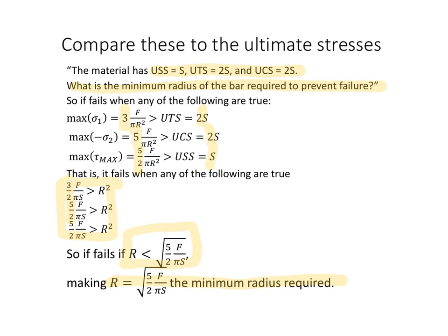So that's this process in brief for one problem. In general, we won't see that the loads all end up in the same type of stress, in this case where they were all sigma x. So in general, we will probably have different contributions to the Cauchy stress tensor from the different types of loads, and we will see examples of that in the lecture.